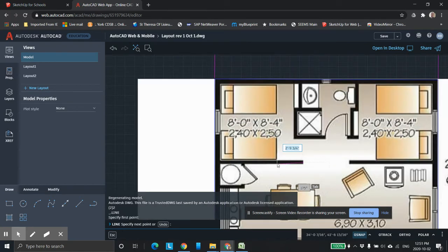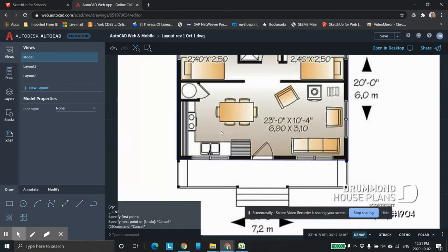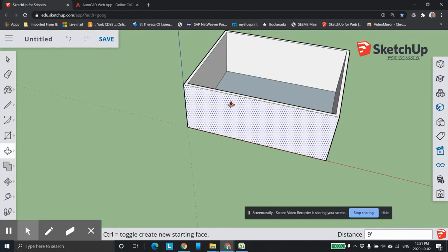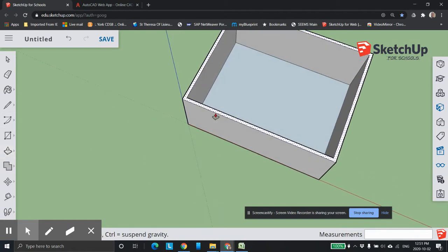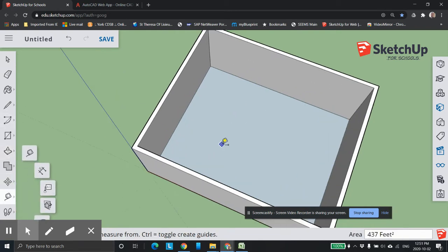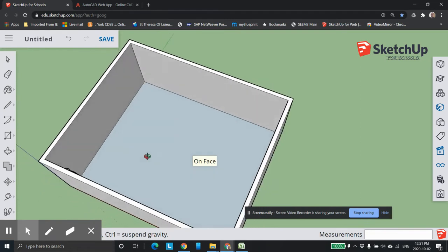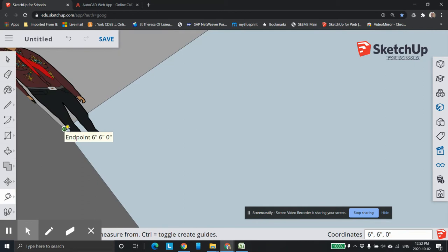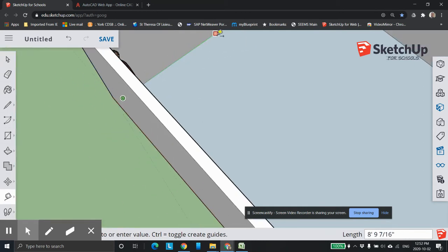We also need to know, hit the escape tool and come up here, how far back it is. It says right here, 10 foot 4 inches. So from the inside here to the inside of here, we'll set it to 10 foot 4 inches. So we just come over here, into here, and let's take the line tool first. Here in the corner, I'm going to delete that guy in a second. I should delete him now. And we're going to come up here. I'm just doing a guide up, and the guide's going to be 10 foot 4 inches. Enter.